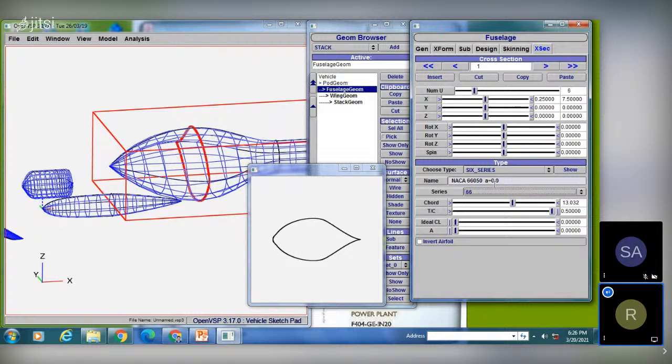So the 6A series aerofoil also falls into this category itself. The aerofoils that come under the 6A series aim to eliminate the sharp trailing edge and cusp that is present in the normal 6 series aerofoil. You have to know that the A value we have here indicates the fraction of the chord with laminar flow over the aerofoil. So you can set it to 100 or 1 by default. Yesterday I told about this, right?